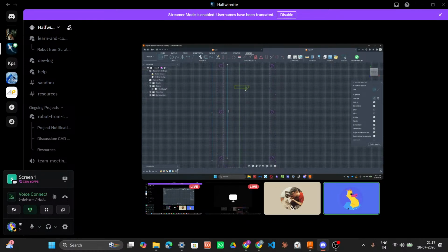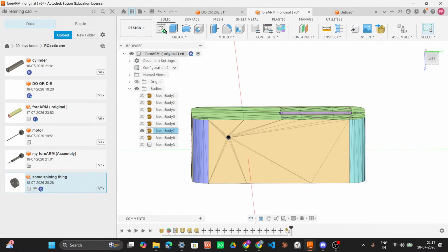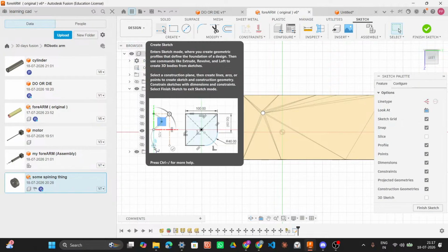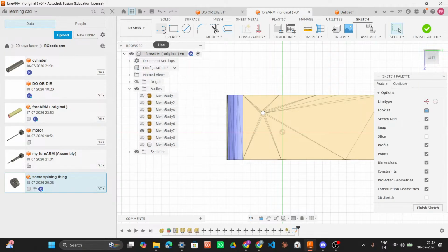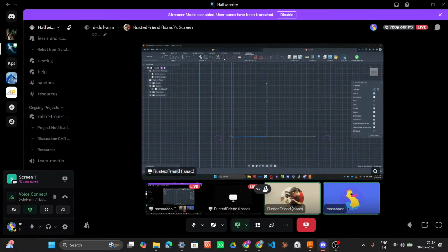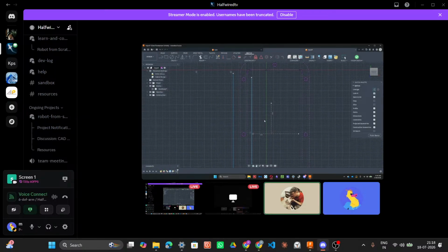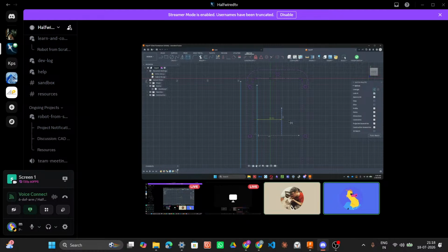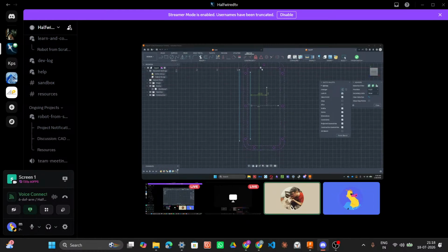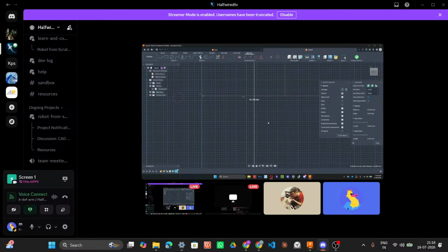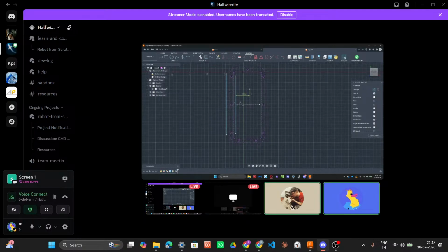So I'm going to give myself basically a reference origin to work from. Midpoint that and make it horizontal, vertical. These should be 20 since I measured 40. And then I'll call that 95.3.